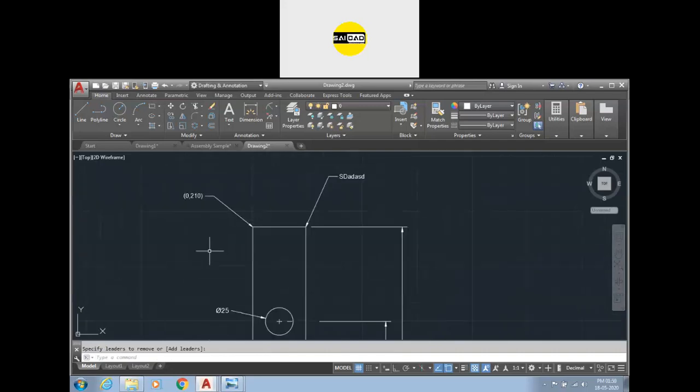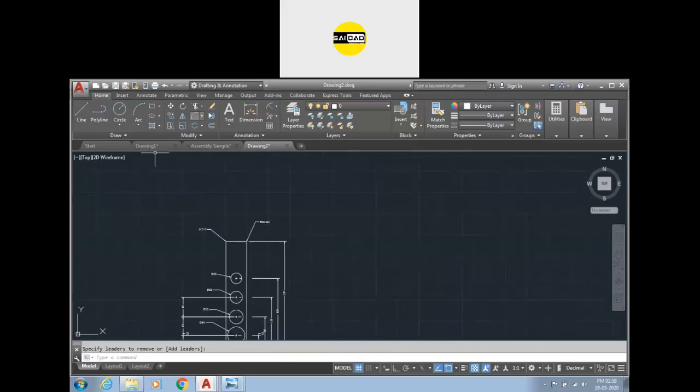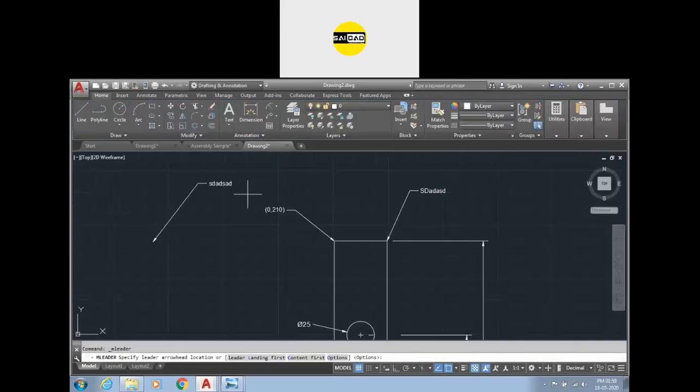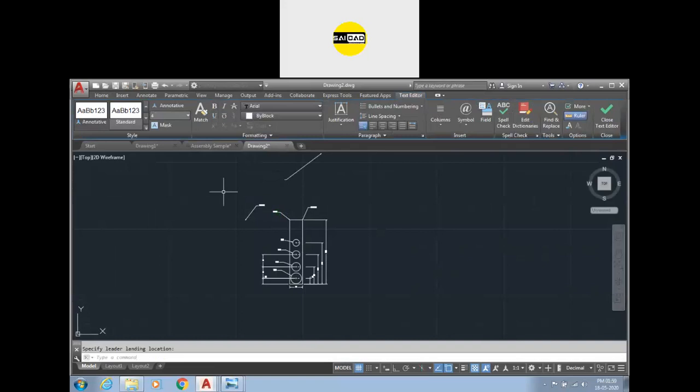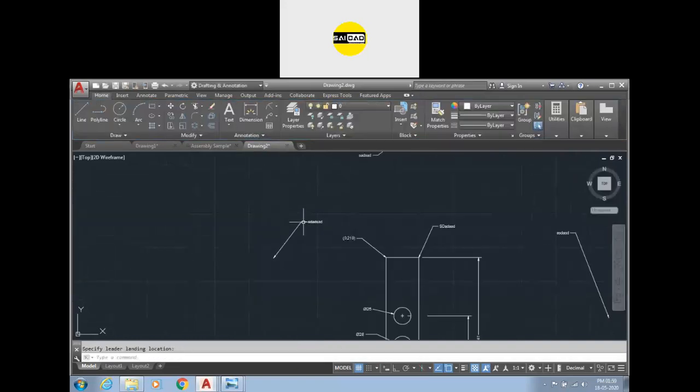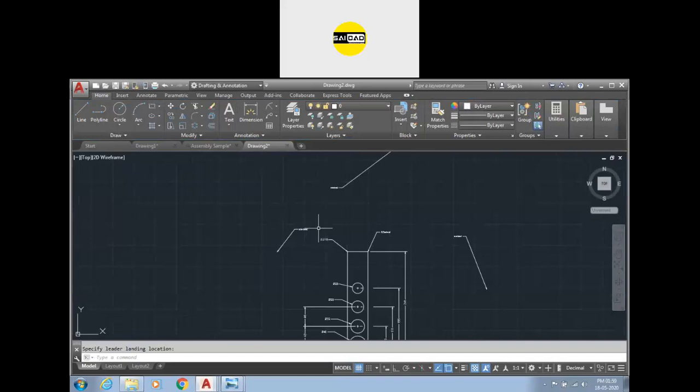Okay, next option is alignment of the leaders. If we have multiple leaders, suppose I have some leaders like that. I want to align all of the leaders in a single line, so I can just use the align type from here. Select the leaders like that, press enter, and select the leader with which you want to align.